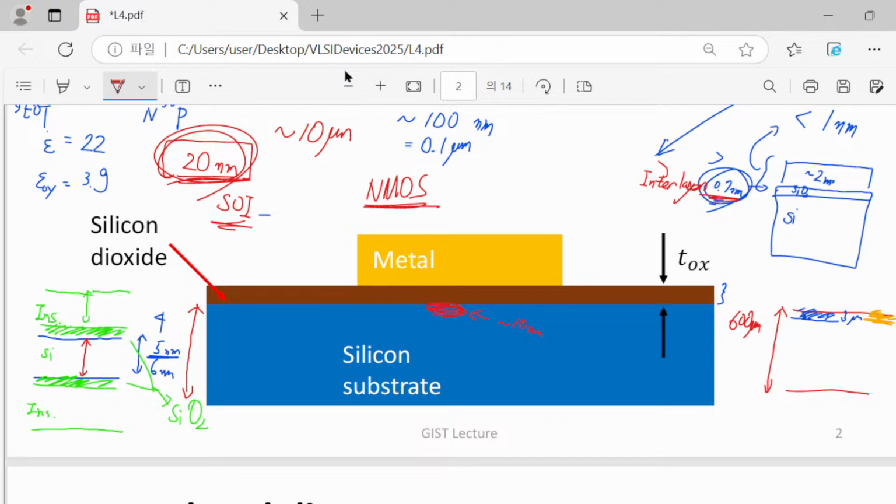So you mean that in this scaled device? So in this scaled device, actually, well, you're right. So in this case, the entire 5 nanometer, 6 nanometer layer is doped with a certain value, because 5 or 6 nanometer is not that long a distance even in our scaled technology, so you cannot make such a variation in your doping profile. A uniform doping profile is assumed.